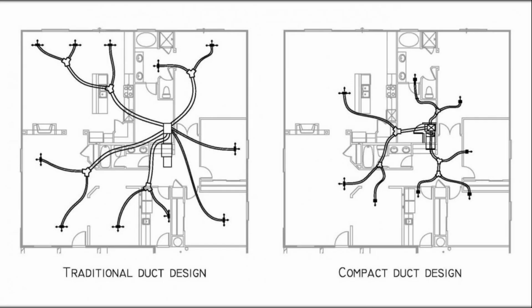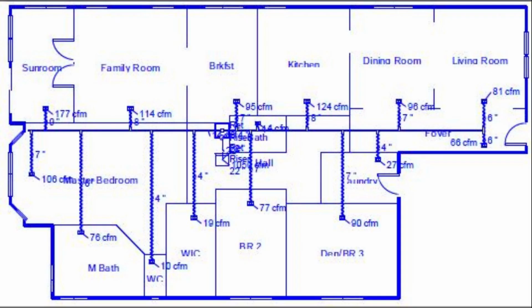Shorter duct runs allow higher velocities without excessive static pressure. Rooms nearest the thermostat often receive the warmest or coolest air, potentially leading to improper cycling. For compact duct design, follow these duct and equipment layout and grill selection guidelines.